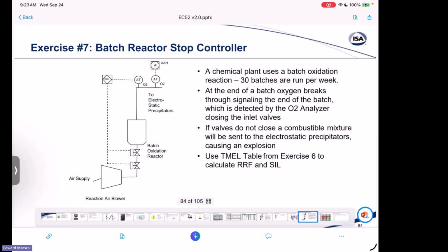So let's say I was testing this safety function once every 2 years. So for once every 2-year test, I challenged it about 300 times. So when the SIS fails, are you going to find out because you tested it and it didn't work? Not bloody likely. You're going to find out about it because you challenged the safety function, it didn't operate, and I had my consequence.